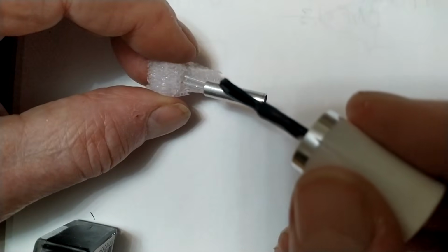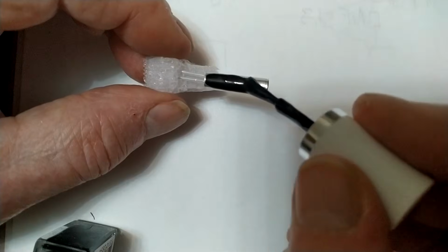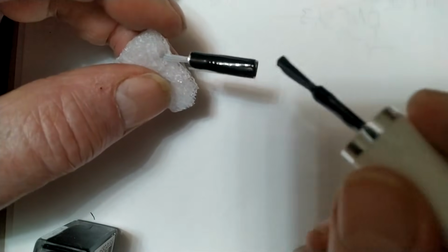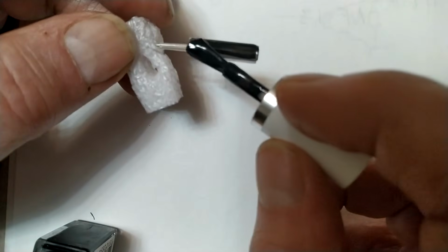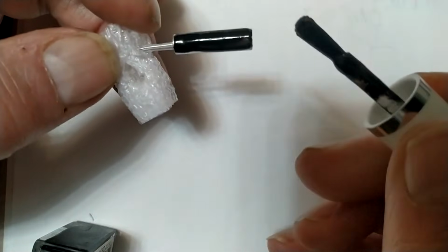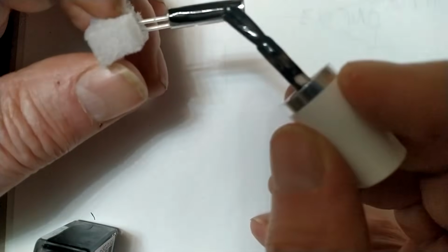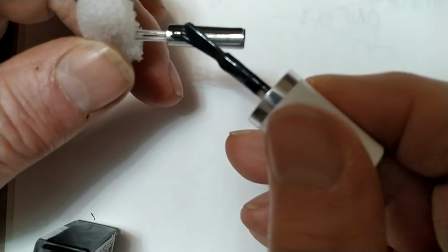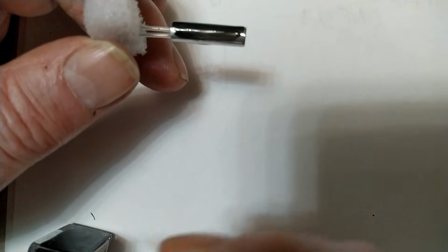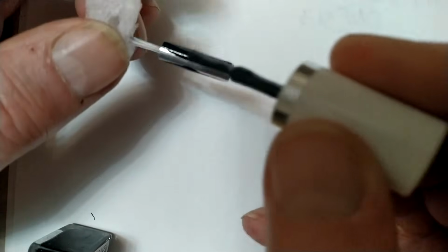I paint the aluminium black because I want the aluminium to take care of heat from the light-emitting diode, and also to screen the light so it only comes in the forward direction. And the black color is to radiate heat from the aluminium to help keeping the temperature low on the diode.